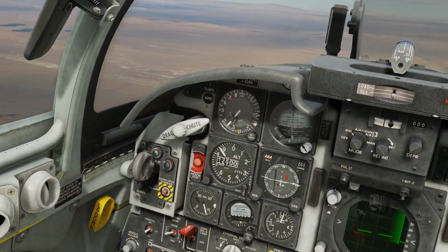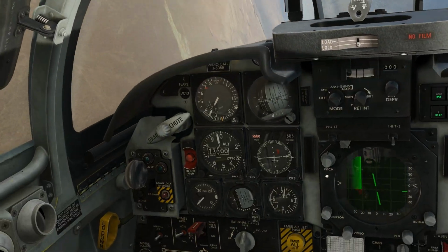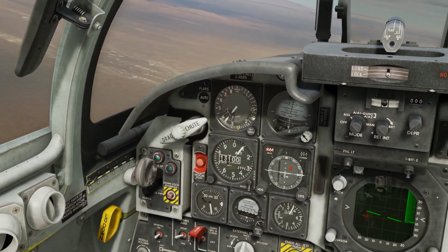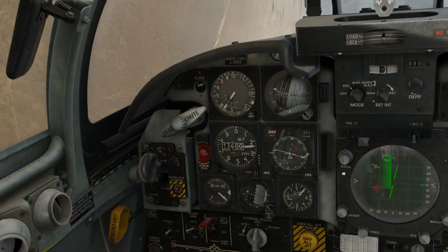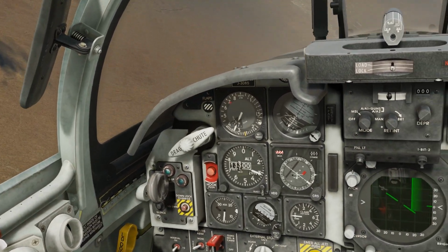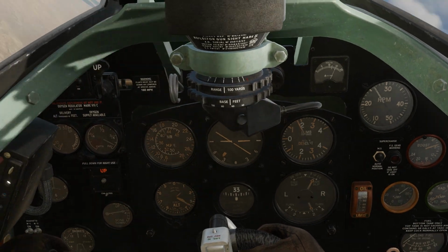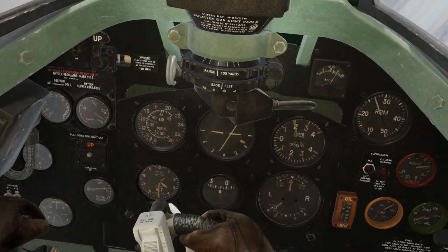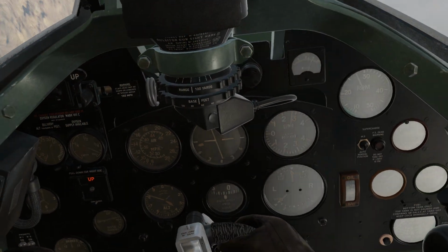Air entering at an angle, or gusts of wind, thermal convections, and side slip will affect how accurate the information is. Also, the construction of the instrument itself, and that of the aneroid capsule, is not perfect. Thus, the airspeed indicator has some corrections built in, but not in all cases, as we can see with the Spitfire.